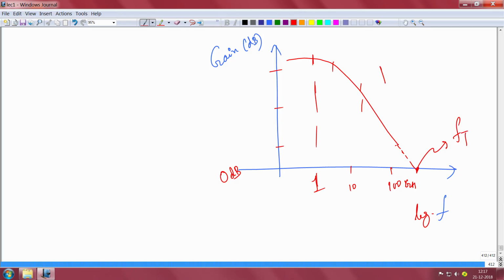Typically there is a parameter called H21, an H parameter that you plot. Let's not go into that. This plot of the H21 parameter is actually like the current gain, and wherever it becomes 0 dB, that point is called your current gain cutoff frequency. Typically that is how you decide. You can do these measurements in a vector network analyzer to find out how the device works.